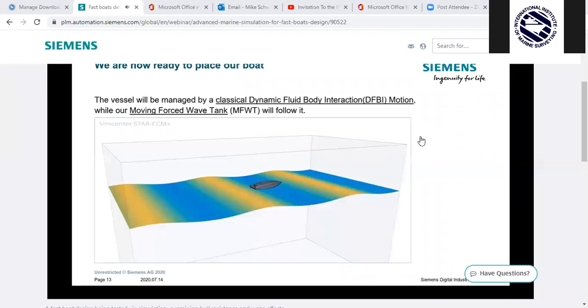And what happens with this is now we have a completely decoupled boat motion from the wave physics, which makes it very easy to implement robust and intuitive setup of any type of wave interaction or maneuvering problems. The motions of the hull are also solved for independent of the wave setup by having two separate regions that are solved for simultaneously. So using this forced waves approach makes setup possible for doing just about anything you could want without having to rebuild your model every time you want to make a simple change.